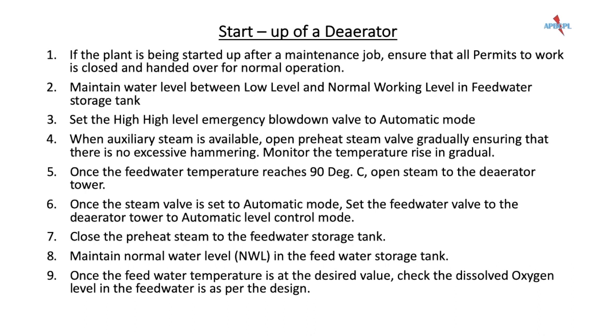Never exceed the design feed water temperature value, as this could result in restricted thermal expansion movement, overpressurization and seizures of boiler feed water pumps.